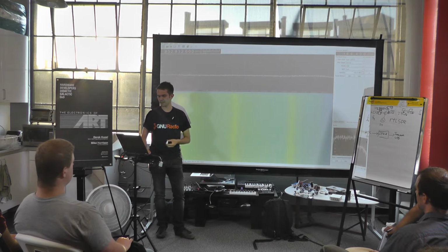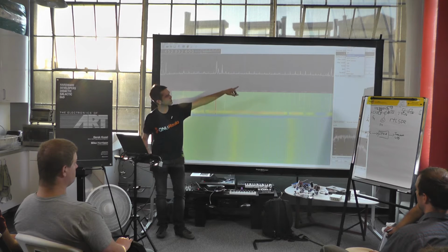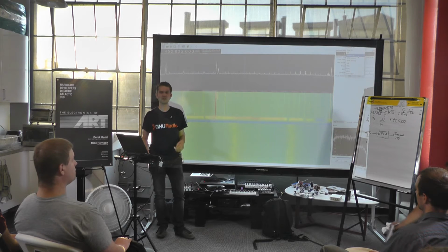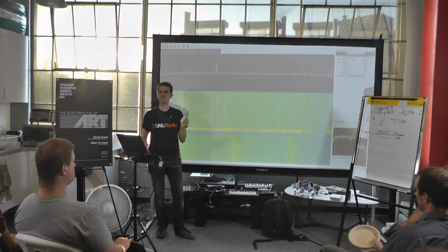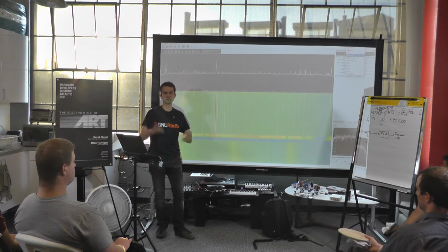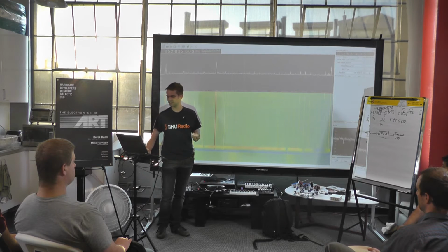And if we go up quite a bit higher, around 450, this is more public safety. This is actually narrowband FM. So what I'm doing over here is selecting the demodulation mode. And this is possible, again, because the hardware doesn't actually implement anything that's required to demodulate the signal. It doesn't know anything about what it's receiving, just that there's something.